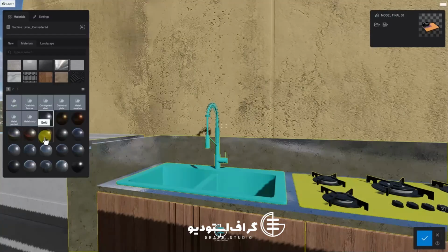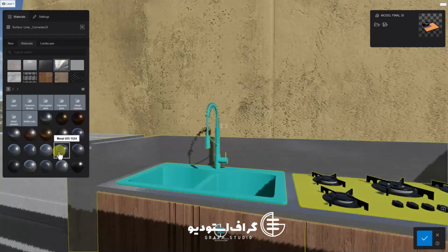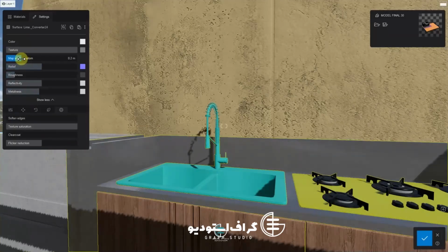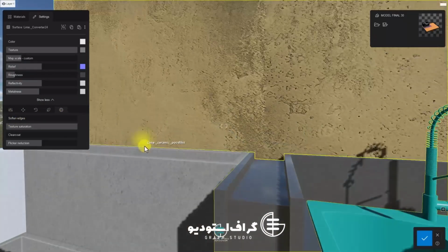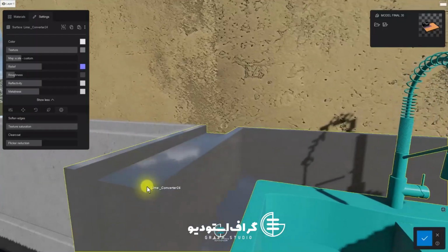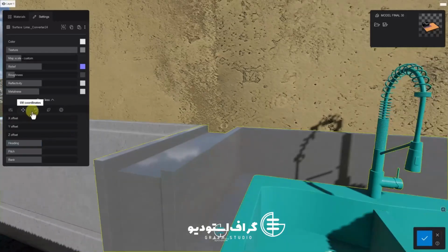Let's make the scale smaller, and here we can use the soften option. I go to settings, soften. It automatically applies a chamfer to these edges. If you see that your model doesn't have enough chamfer and is this sharp, that's very bad. We said we shouldn't have very sharp edges, so we can do this cool trick inside Lumion through the material settings. It turned out fantastic.